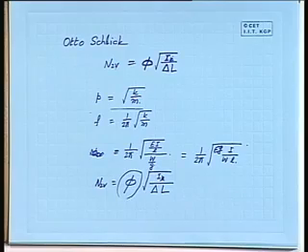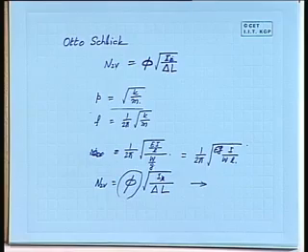And then he said that if you are going to analyze this type of a ship, then assume phi is equal to so much. If you are trying to analyze a tanker, then phi is so much. If it is a cargo ship, phi is so much. And this continued for about a century. Even today, when we are trying to find out in the initial stage the natural frequency of vibration of the hull girder, we use this type of an equation only. We will come to it a little later.